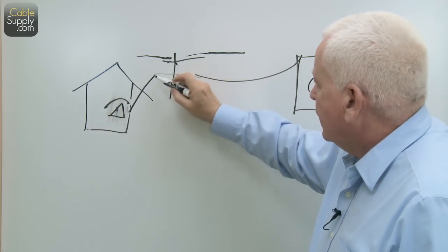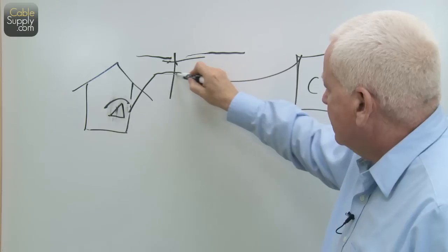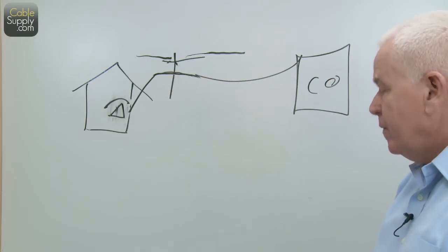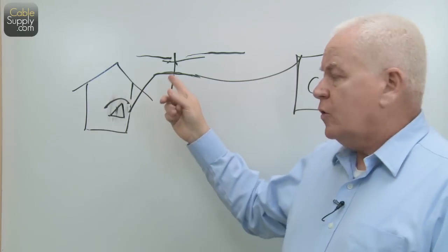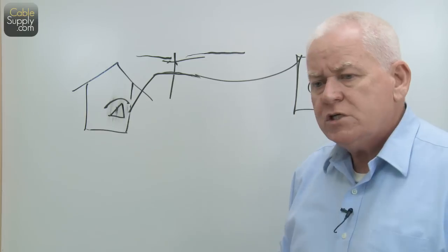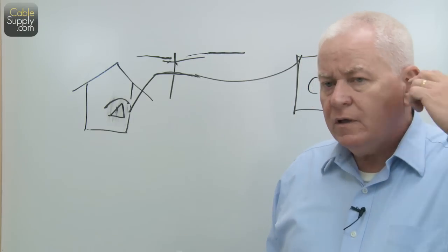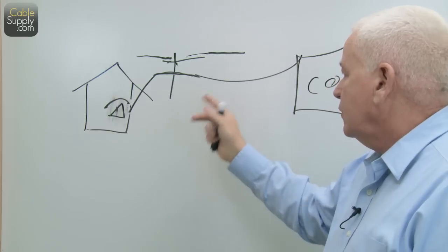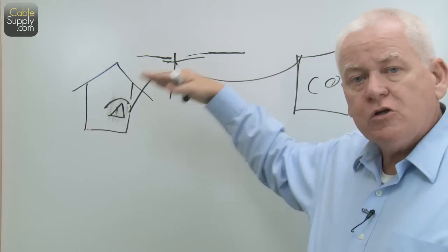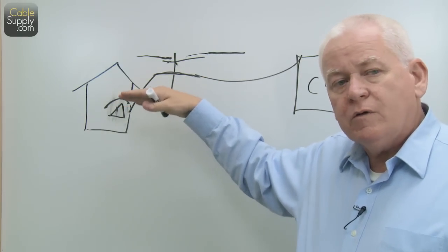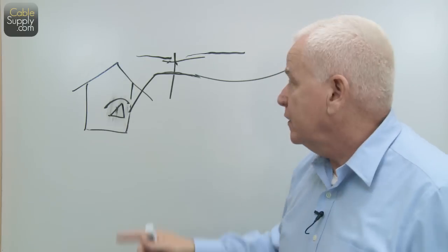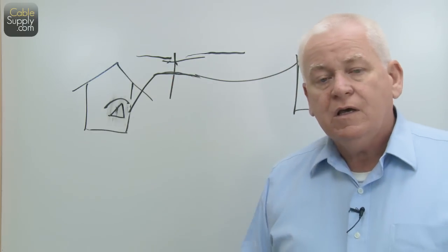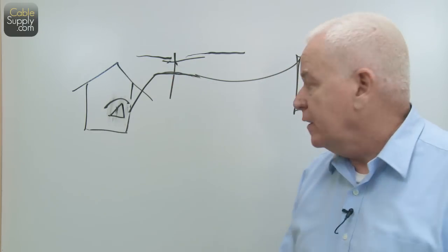So these are relatively safe. You've got low voltage here. In some cases it's a little high for certain circuits, but overall, telephone voltage is 24-48 volts DC in that area and that size. So it's nothing to really be concerned about, and that's why it's lower on the pole. So if the guy's out there working on telephone lines, he's not accidentally touching the high power lines or the house lines.